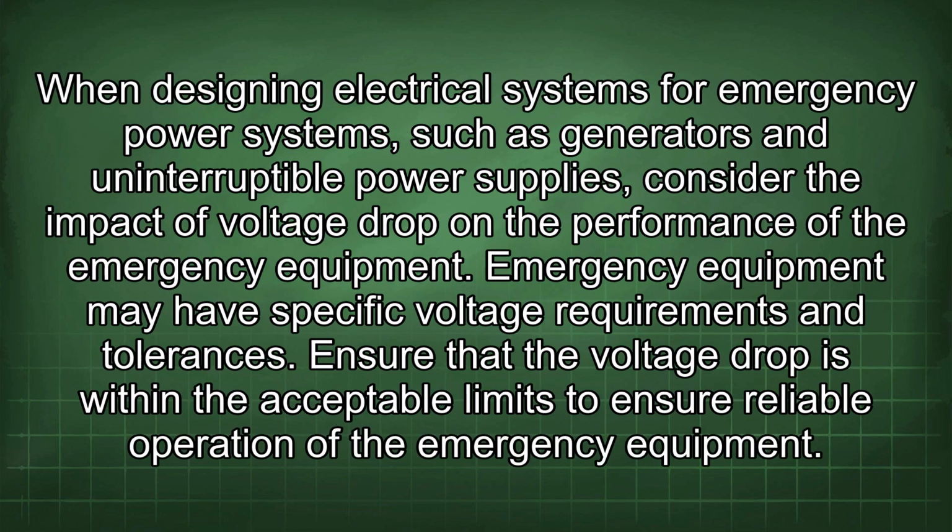When designing electrical systems for emergency power systems, such as generators and uninterruptible power supplies, consider the impact of voltage drop on the performance of the emergency equipment. Emergency equipment may have specific voltage requirements and tolerances. Ensure that the voltage drop is within the acceptable limits to ensure reliable operation of the emergency equipment.